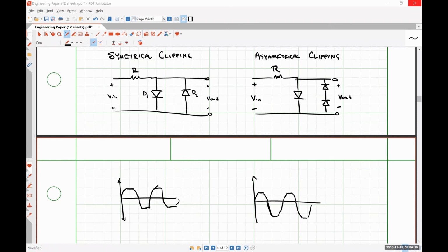Now, your solution. Analyze a simplified design, so use the ideal op-amp model to make sure things are going to behave the way that you expect them to behave. Run a couple of simulations. Make sure everything's working right. Then start making notes about what elements are critical to the requirements. So for instance, it says here, make a note of the max reverse voltage applied to any diode of your circuits.